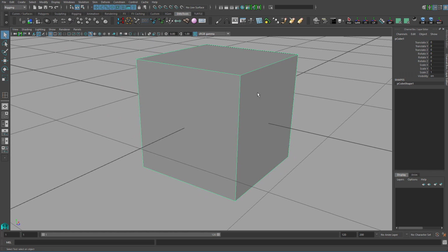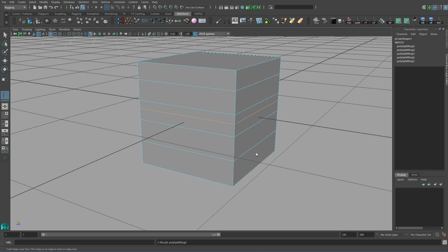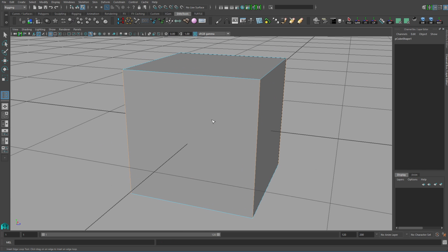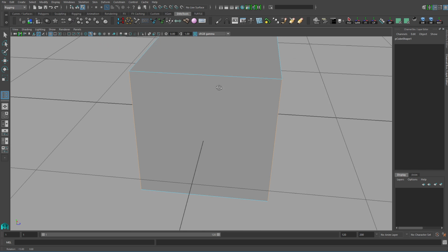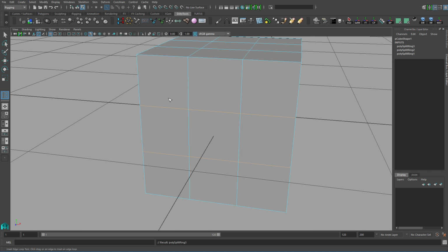Okay, enough of that. Let's move on to some detail of Insert Edge Loop tool. In the default settings, you can click and drag there to create edge loops. But when you're in this tool, you can hold down Control and Shift together and right mouse button, that brings up the settings of this tool. Now, for example, I can create multiple edge loops, and I can create 2 of them, and then when I click on that edge, it actually creates 2 edge loops for me.